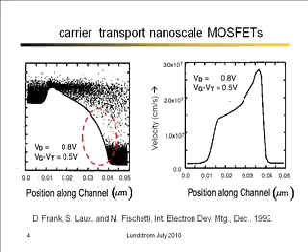Now, if you've seen transistors before and taken courses, one of the things that you'll remember is that the slope of the energy band diagram is the electric field, and the electric field is very strong near the drain because the slope is very steep. And one of the things that you learn in basic introductory semiconductor courses is something called velocity saturation. When the electric field in bulk silicon gets very high, electrons scatter a lot, and you approach a saturated velocity that's almost exactly 1 × 10⁷ centimeters per second.